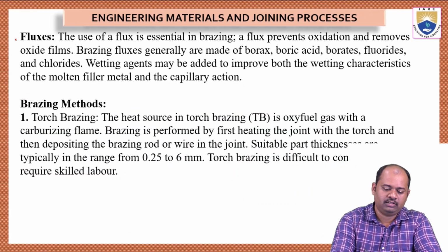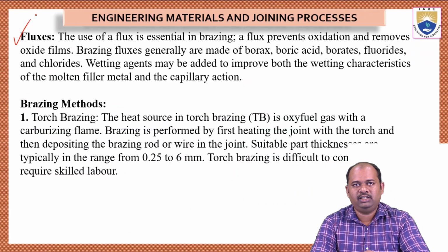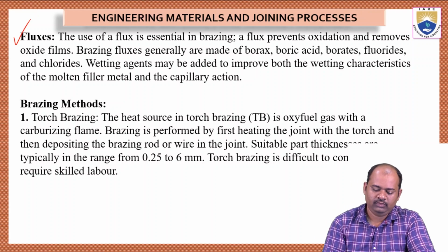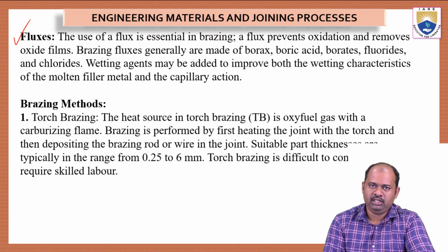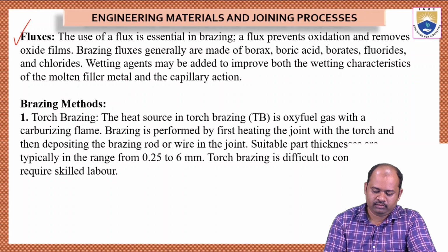And then we have fluxes. Now we should know what a flux is. Flux is a material essential in brazing. A flux prevents oxidation and removes oxide films. So when we are trying to form a joint,